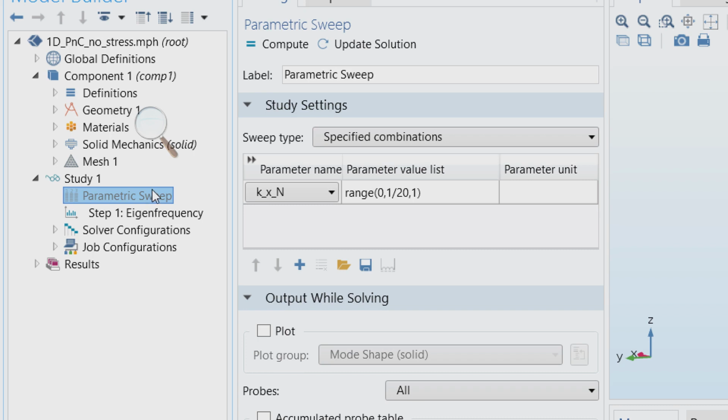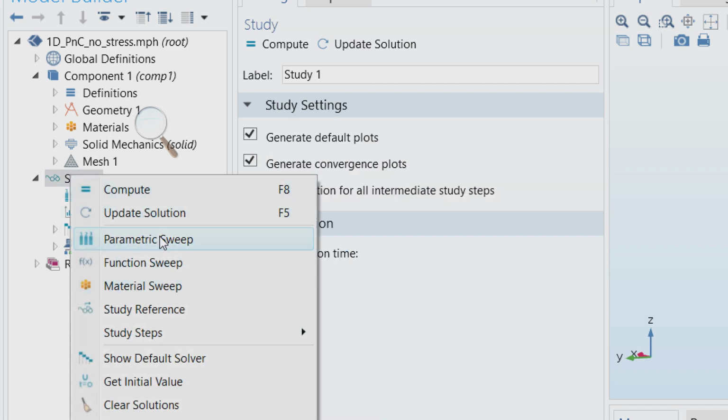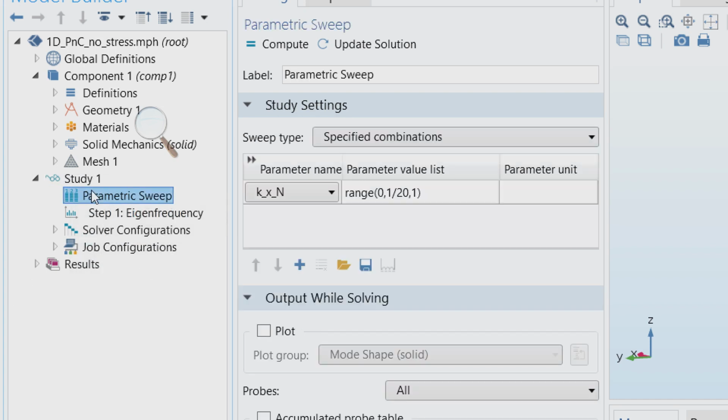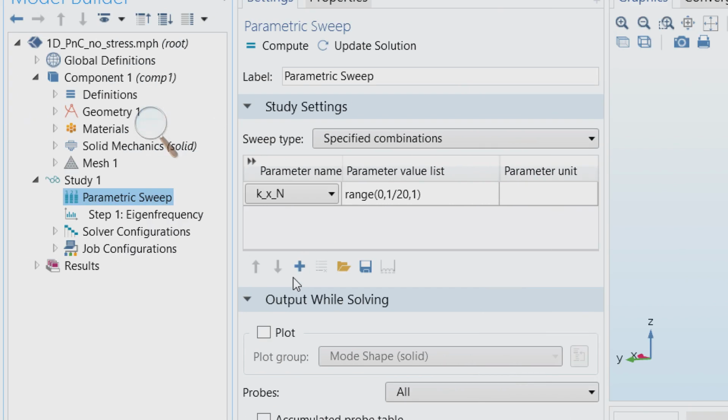And keep in mind that the silicon nitride was a high stress material, but I did not do anything regarding the stress profile and the stress release. So here we're actually doing a wrong simulation, but I want to show you that if you simulate it like this, and then if you add the effective stress, your band gap actually is different. So it's about to finish. So here you see that it's good and converging, and I didn't do anything about that. It's automatic Newton convergence. So we'll go for the 20 k vectors that it's supposed to.